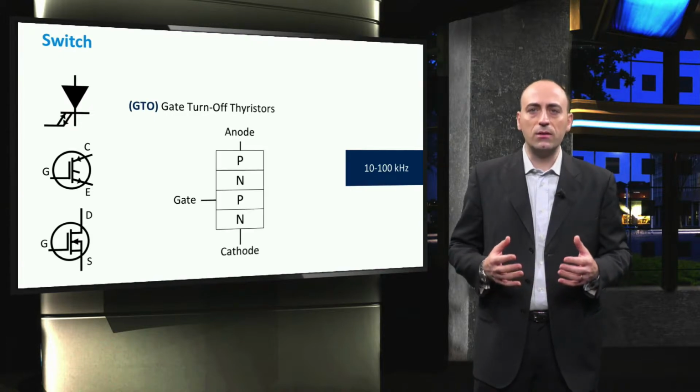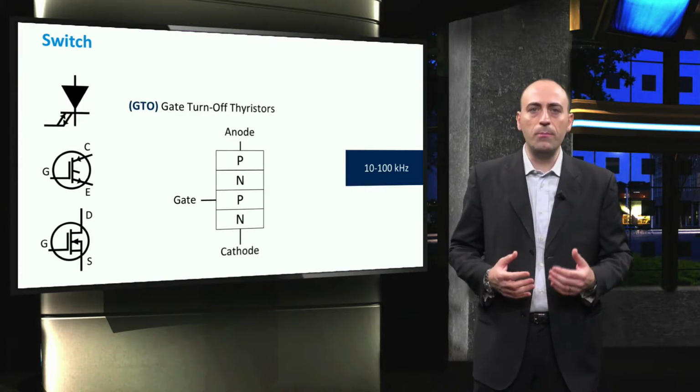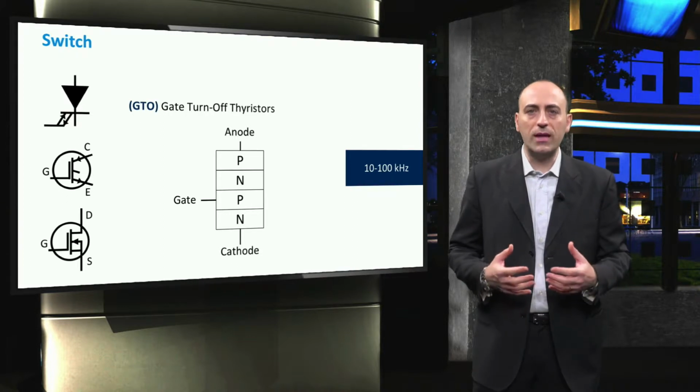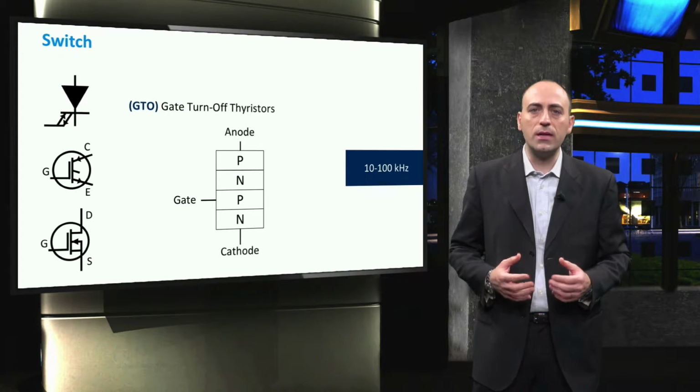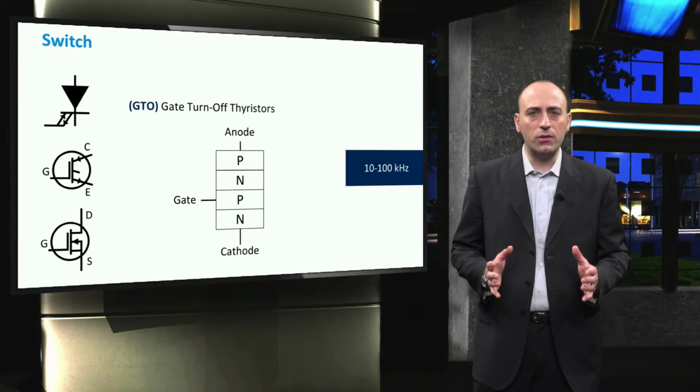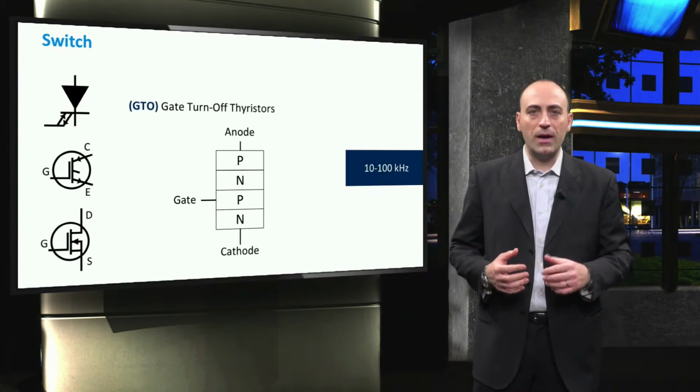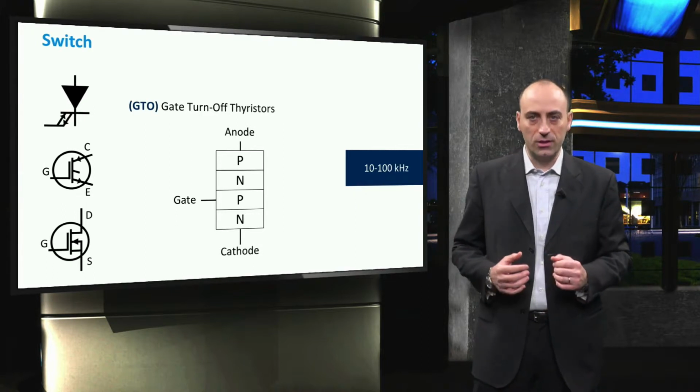Thyristors are electric components consisting of three p-n junctions, which operate as bistable switches. One disadvantage of these components is that thyristors cannot be turned off, but only turned on by applying a signal to the gate. Such switches lead then to a very high harmonic content, requiring additional filters in order to make the output compatible with the electrical grid.